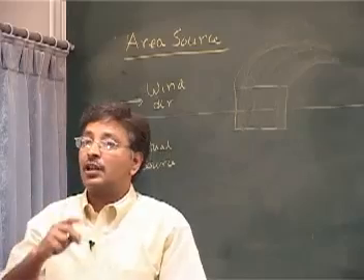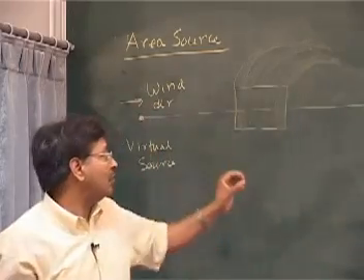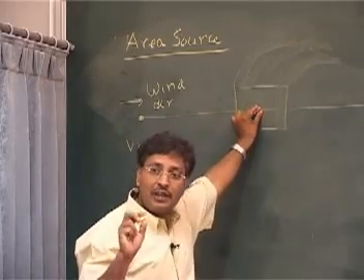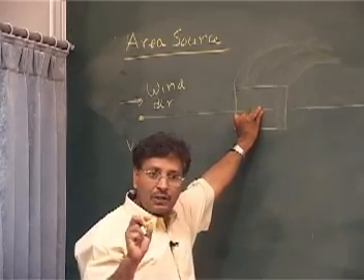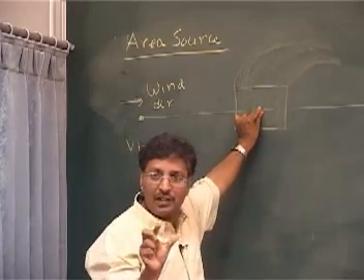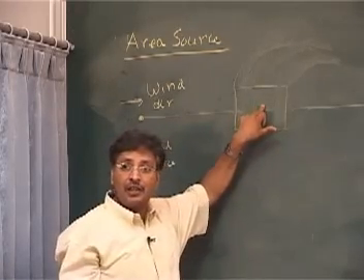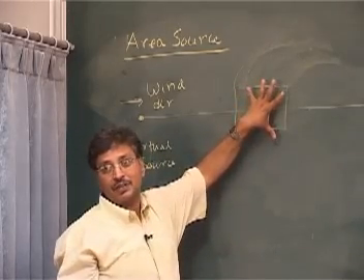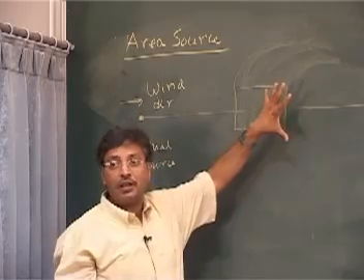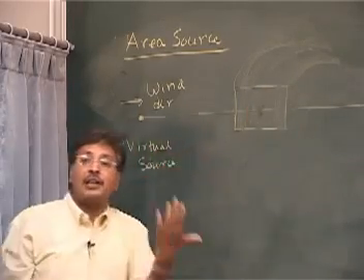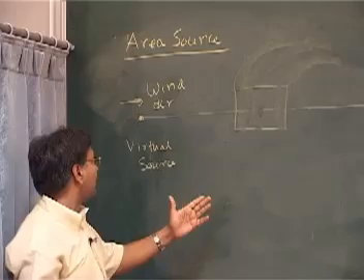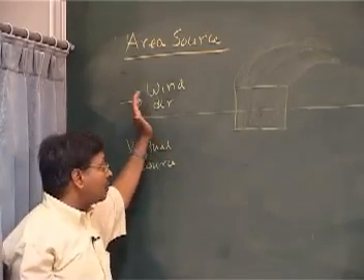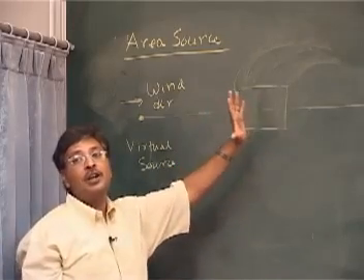But then is it a real approximation? Then you are saying the chimney is located here, okay, and at the tip of the chimney your sigma y and sigma z are nearly 0, right? The spread in the plume is nearly 0. Is that correct here? This is not correct. Sigma y and sigma z in the sources, there is already some sigma y and sigma z. Okay, so there is a spread already. It tantamounts to saying that there is a source which was a point source, but by the process of the wind transportation it has already spread to something.